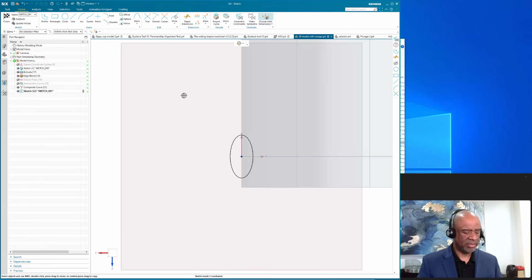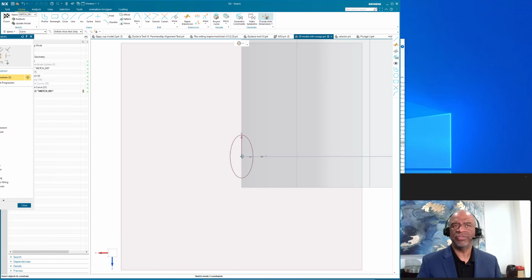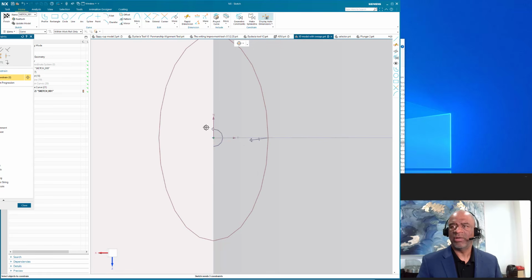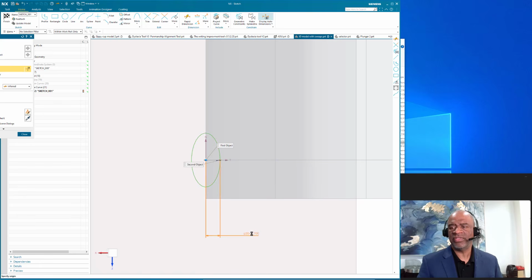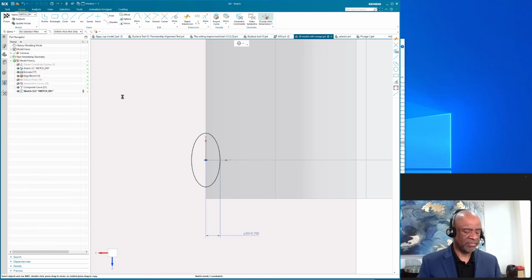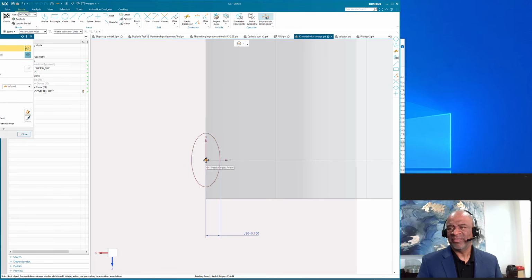And when you do an ellipse, you do have to constrain it with a horizontal constraint. As you can see, there's a rotational degree of freedom here, and you want to get rid of that. And once you do that, then you can feel free to put dimensions on it. If you start putting the dimensions on this sketch, on the ellipse, before you constrain it in that way, it'll start rotating and going, for lack of a better term, cockeyed. It's a technical term, cockeyed. And I'm going to put 2 dimensions on here.